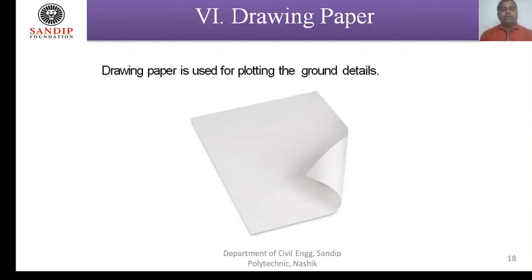And last is drawing sheet. To draw any survey work or any drawing, we require a drawing paper. So we generally use an A2 size drawing sheet, which can be accommodated on the plane table and which is clamped by clamping pins.